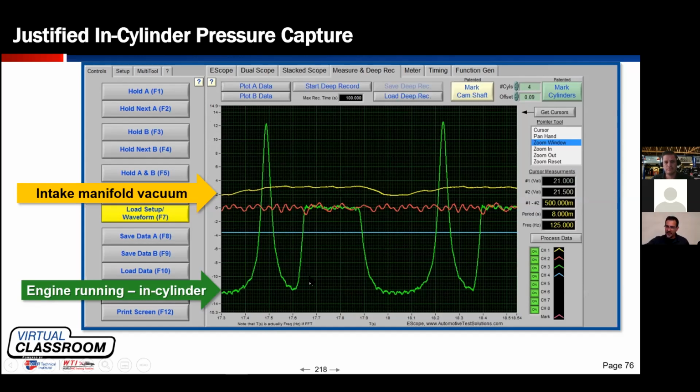But do we have a leak in the cylinder? Yes or no? No, we don't have a leak. And how do you know that? The pockets, right? Straight towers and even pockets. We know if we had a leak, it would go like this.